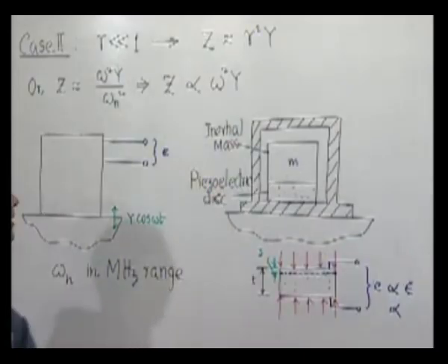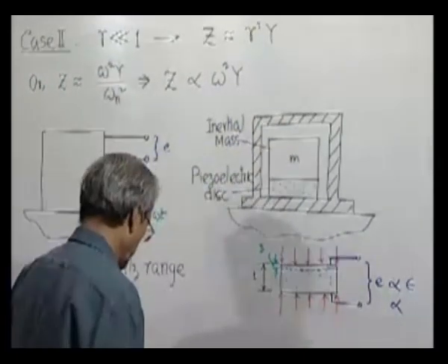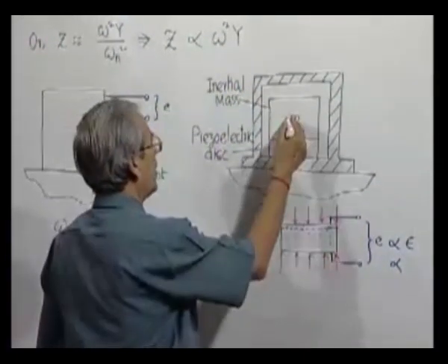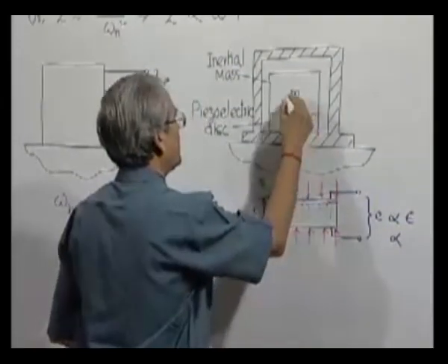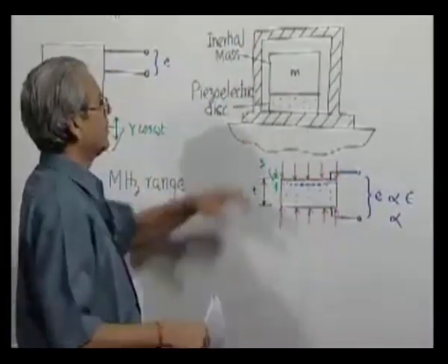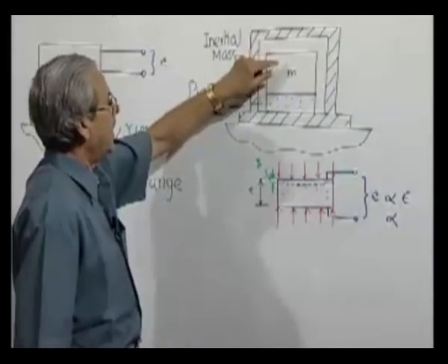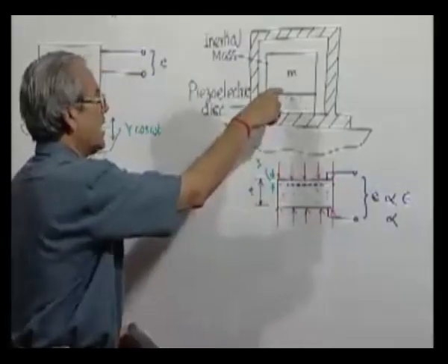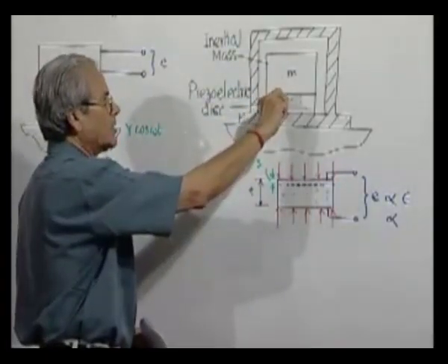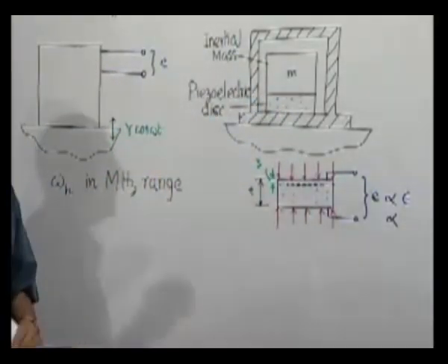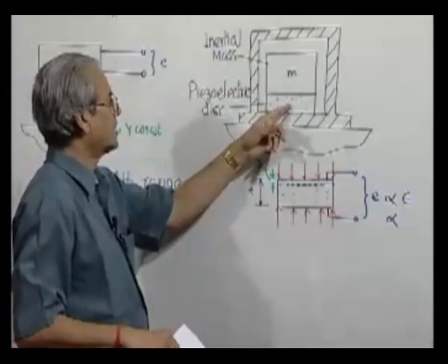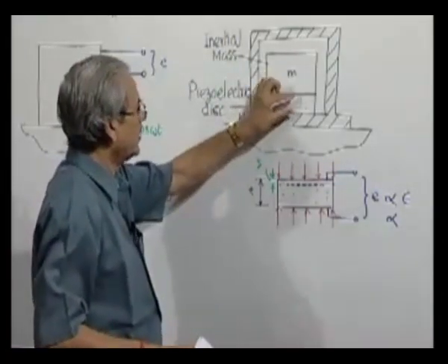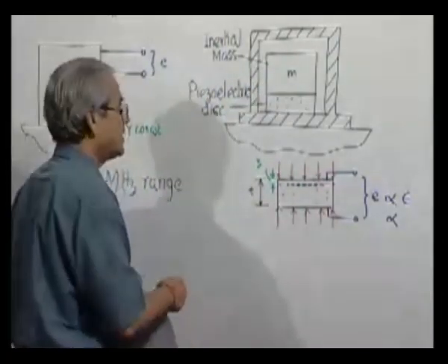So, due to inertia force, which is m x double dot, this inertia force will cause compression or deformation of this piezoelectric crystal, and that will generate a voltage.